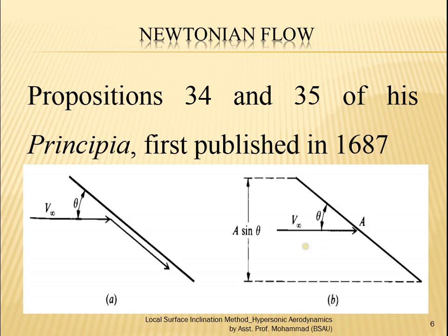So he saw that when this stream came and attacked, after attacking it turns and becomes parallel to the solid surface, no matter what the angle of inclination is. So he observed and concluded that the striking surface particles will lose their momentum normal to the surface, but move tangential to the surface, and hence there will be no loss in the tangential momentum.